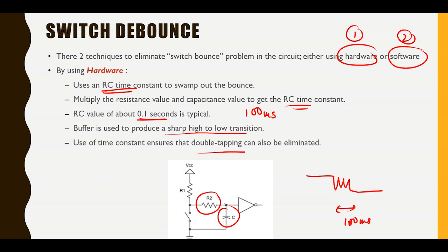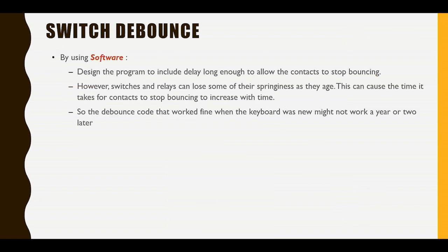But if you need this for each pin, it will be a bit of a hassle, because you need to design the PCB with a lot more components. And with a lot more components, your production cost will increase tremendously.